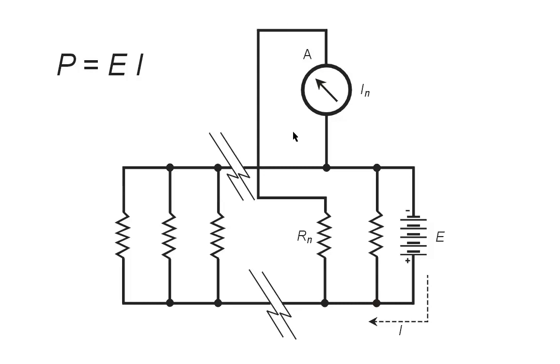Okay, so remembering now, in a parallel circuit, the voltage across any one of these resistors is the same as the voltage across any other of these resistors, namely the battery voltage E. But the currents through the resistors are different, depending upon, of course, their ohmic values. We can calculate using Ohm's law, I equals E divided by R sub n for each and every one of these. If the values are all different, that would make the situation a little complicated to calculate numerically, but here we're dealing in generalities.